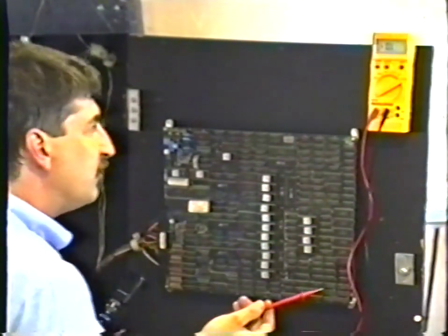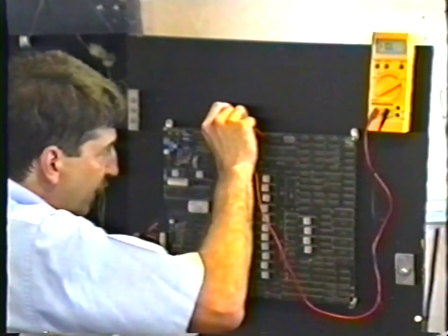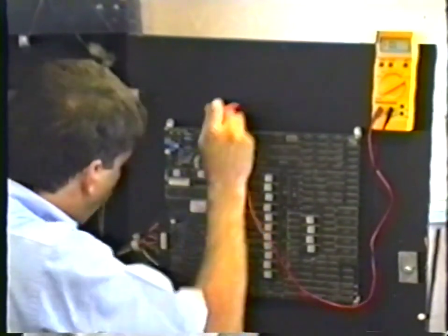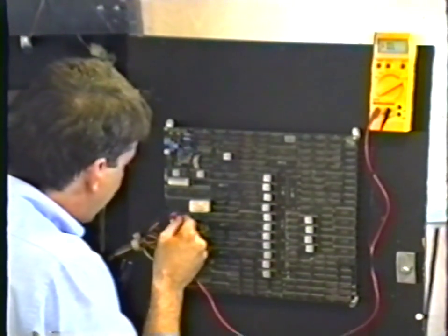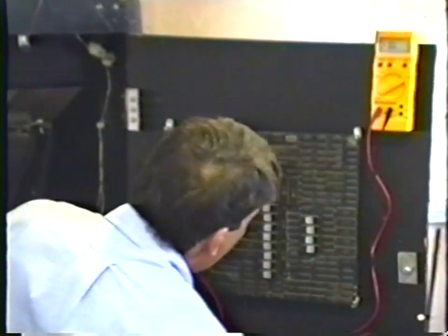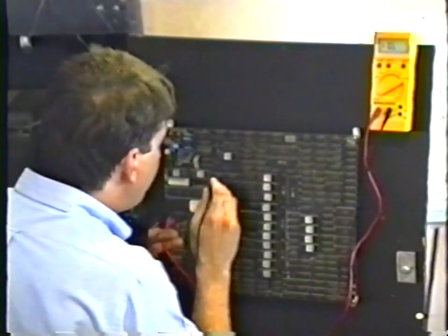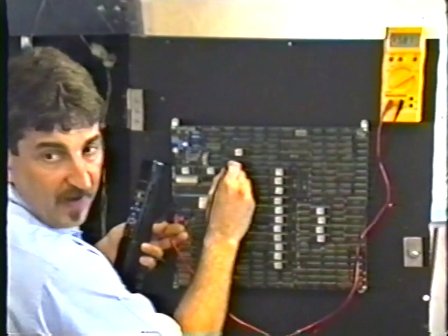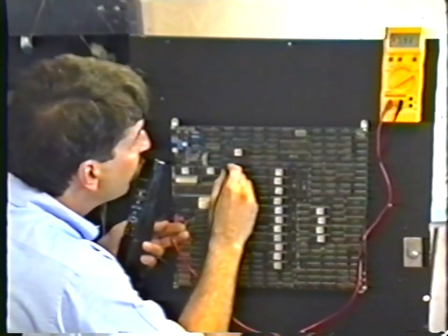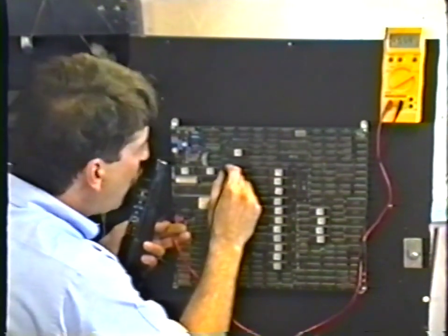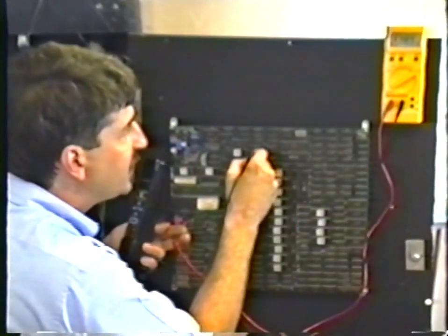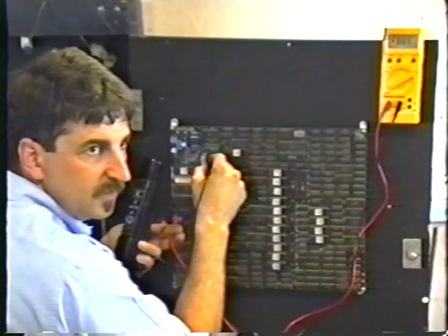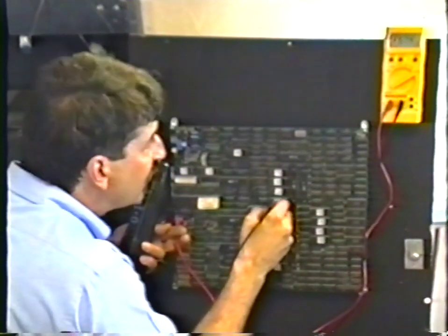So you need to find a ground somewhere. Well, we know that that corner pin of the integrated circuit is ground, right? And if I ground it on one IC, I'm grounded everywhere. Or I could put it over here on this ground. It doesn't matter. Just get it on ground somehow. When you probe the pins of the integrated circuit, you see a junction drop. Like now the meter says 0.5. No matter where I go, I'm going all over the place, and I don't even know what these pins do. 0.5. I've got no idea what these pins really do. 0.6. Do you see how they're all checking like transistors?